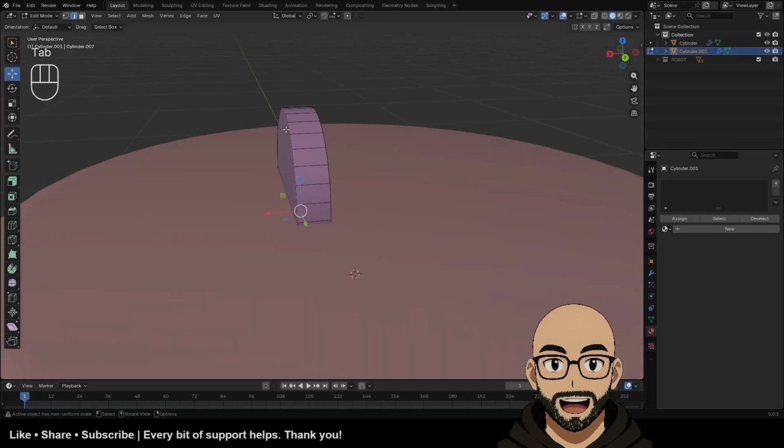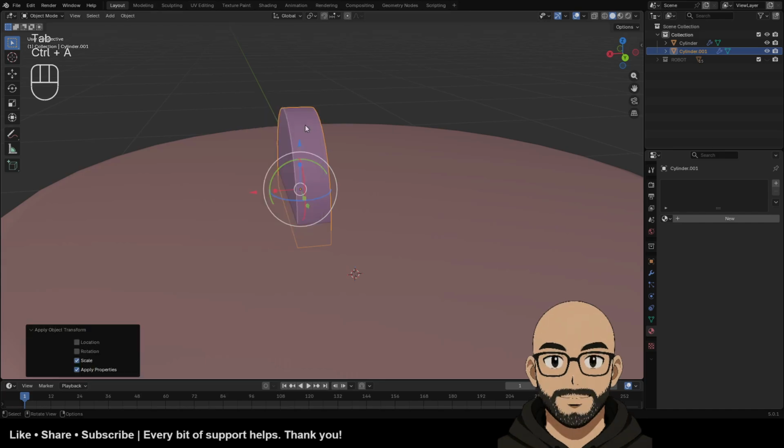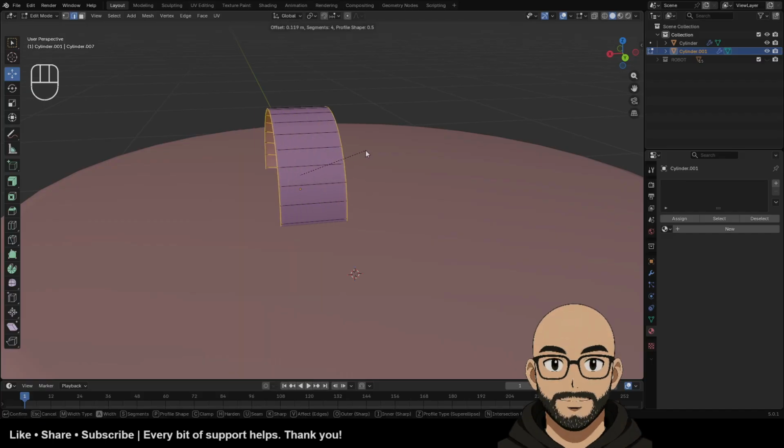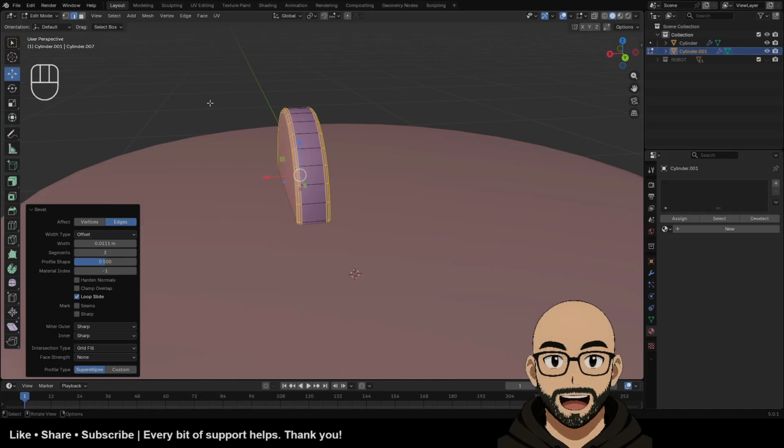I want a little bevel on this too. I'm going to select this edge loop and this edge loop. I'm going to go here, Tab, apply the scale on the transformation, then I'll go back to edit mode. Then I'll do the bevel edges and just reduce the number. I think 3 is okay.